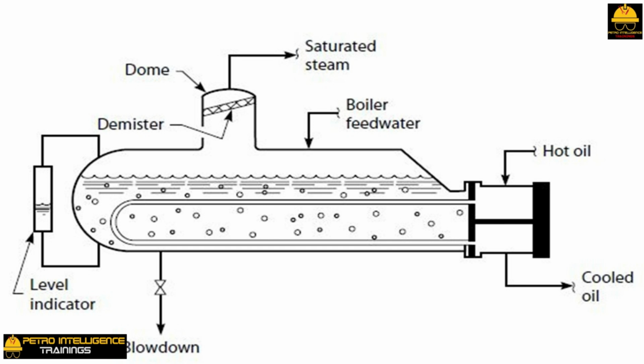To compensate for this problem, the top tube of the tube bundle should be kept well below the top of the kettle. This also will help retard entrainment of boiler feedwater in the steam. To further improve the steam quality, the experienced design engineer places a dome, as shown in the picture, on top of the kettle. The dome will have a sloped demister mesh pad. A demister acts to coalesce small droplets of water into larger droplets. The larger droplets easily settle out of the flowing steam. The demister is sloped to promote liquid drainage from the surface of the pad.